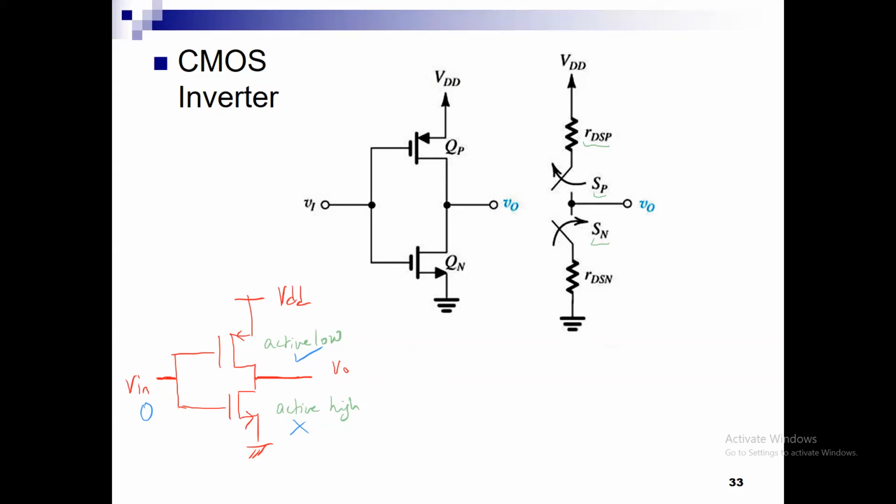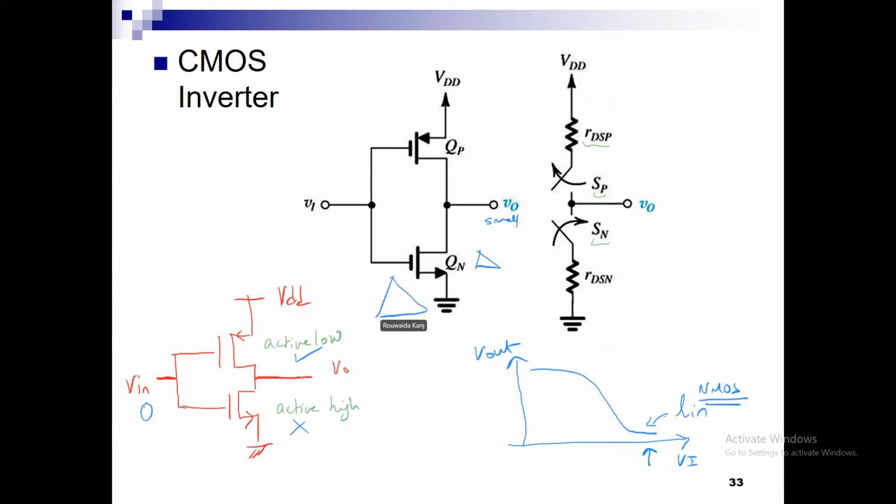if you recall when we talked about the voltage transfer characteristic, we said that in the resistor-based inverter the NMOS is in the linear region when Vout becomes low, because if Vout is small, the VDS is small. Here I have Vn, so Vn is high and the output is small, VDS is small. So the NMOS, when it pulls down, is in the linear region, and we will study these cases in detail later.